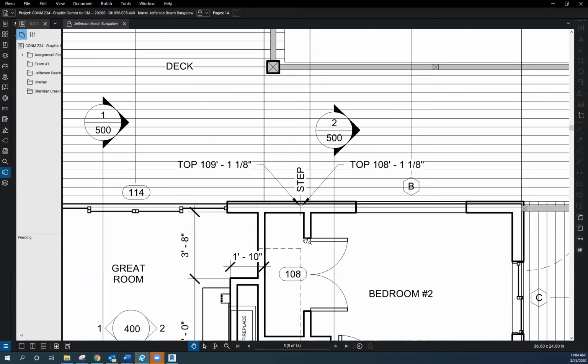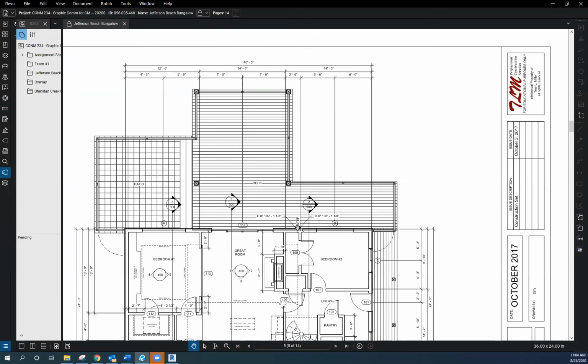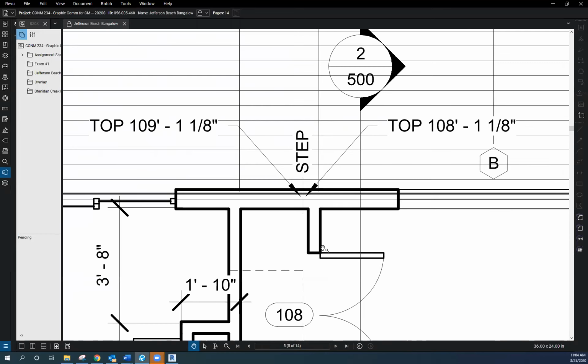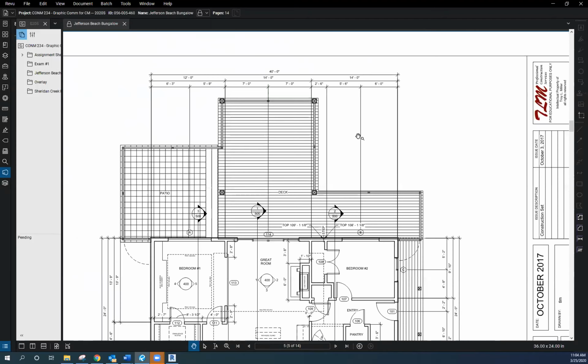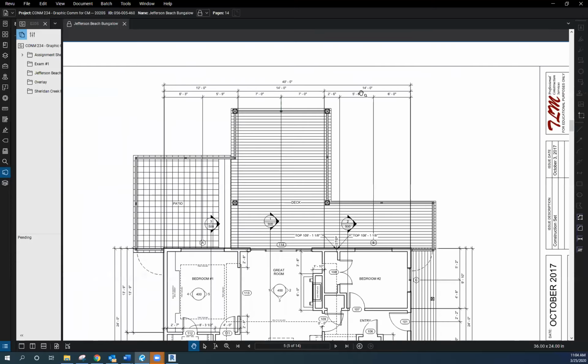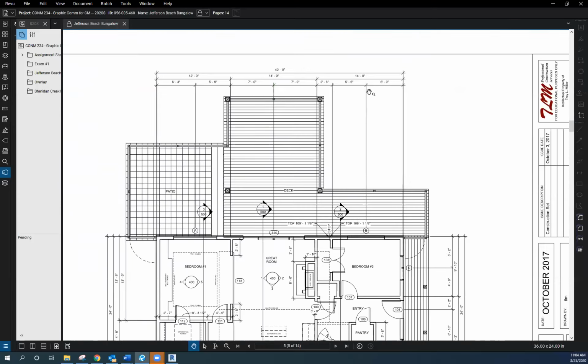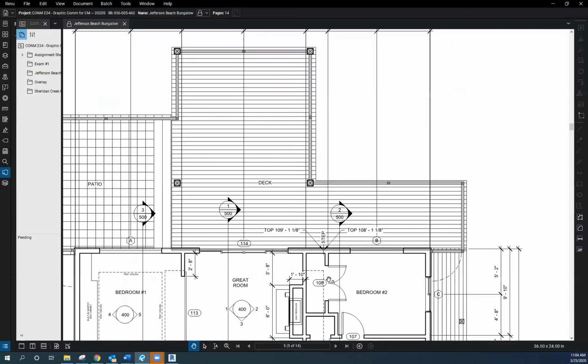So here's what we do know, and I can tell you the intent right here. We know that the front side of this wall is 6 plus 5'6", which is 11'6" to the face of stud of this wall. We also know that this is a 2x4 wall, which measures 3.5 inches. So that's going to put us at 11 foot 9.5 inches.